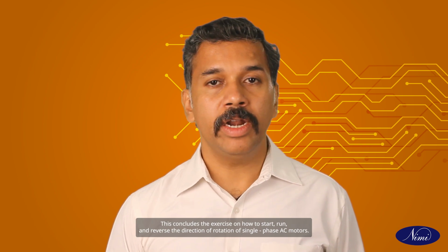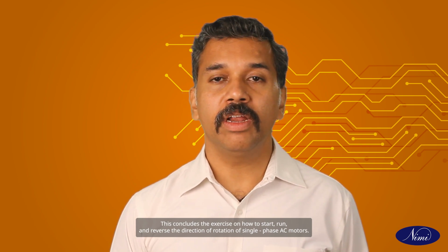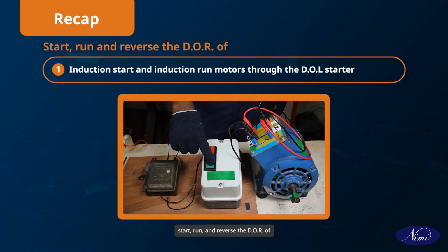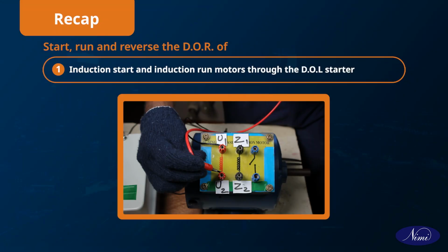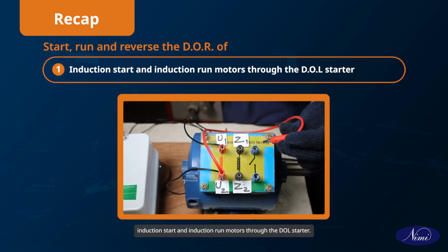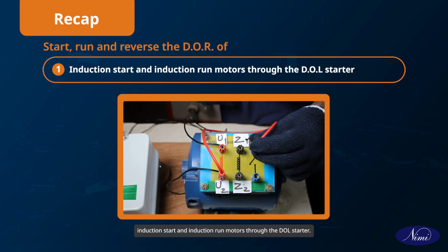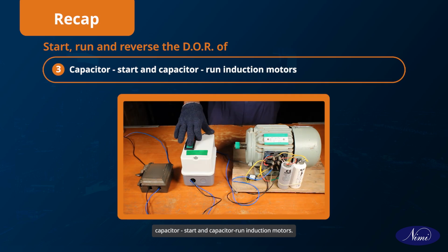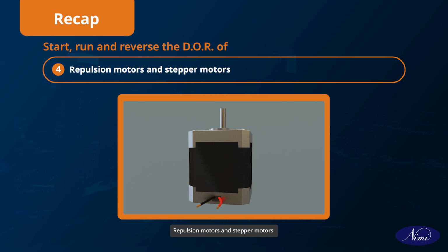This concludes the exercise on how to start, run and reverse the direction of rotation of single-phase AC motors. Hope now you will be able to start, run and reverse the D.O.R of induction start and induction run motors through the DOL starter, capacitor start and induction run motors, capacitor start and capacitor run induction motors, repulsion motors and